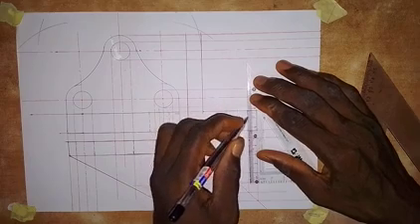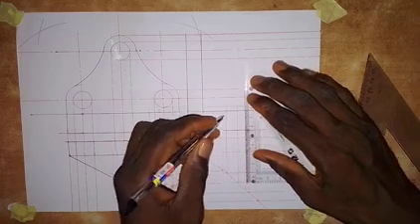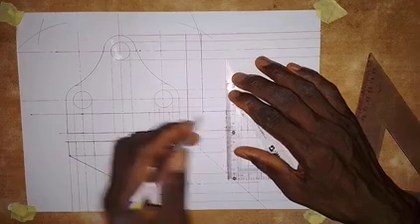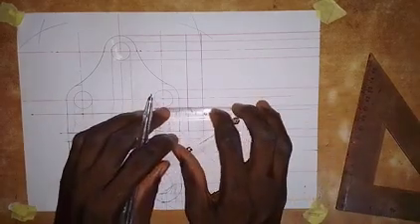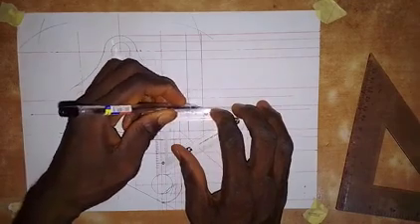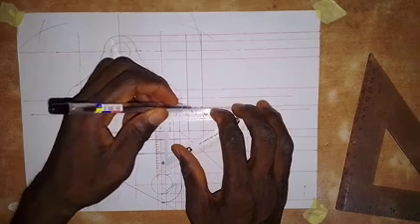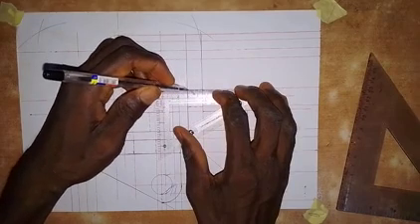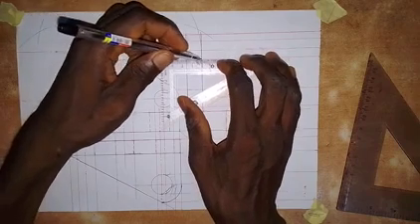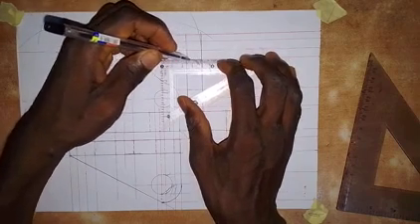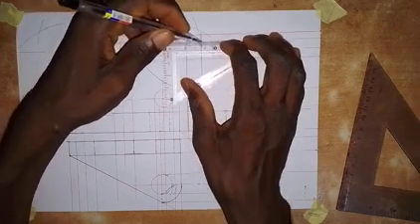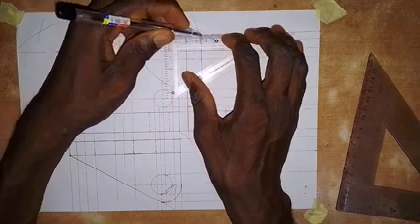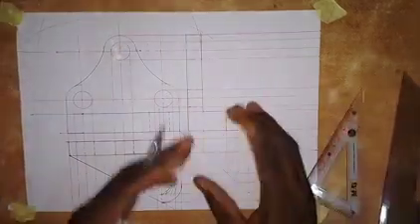Within this part, we make it a short dashes line, and we also make this one a short dashes line like this. Okay, so for this hole that we have here, this is where we have it. So we are going to make it a short dashes line within this part, and then we also have the same thing here. Okay, then up here we also have the same thing. Then we also have this, and we make this line a thick line from here to here. So this gives us the end elevation.